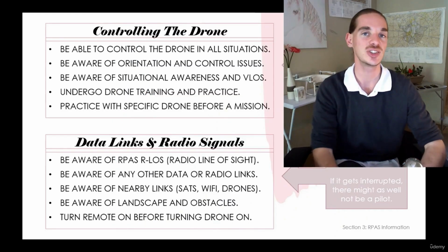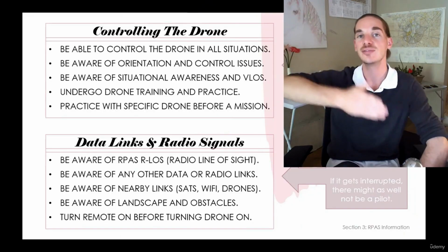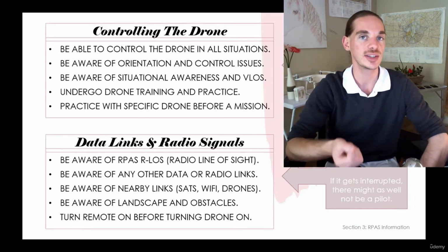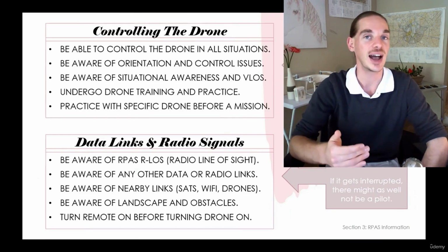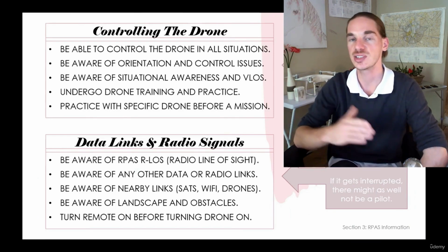Now let's talk about an internal separation of data links. If I have a C2 link on 2.4 gigahertz and I have a camera on my drone and a screen on the ground, they also have to connect through a data link, right? I can't have a wire running from my screen on the ground up to my camera in the air. It's going to be an invisible connection, another data link. However, I might not want it on the same frequency. I don't want that on 2.4 gigahertz.